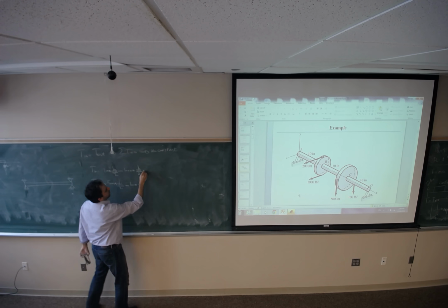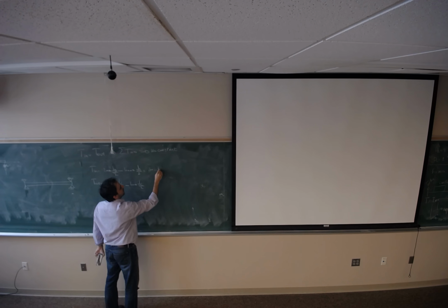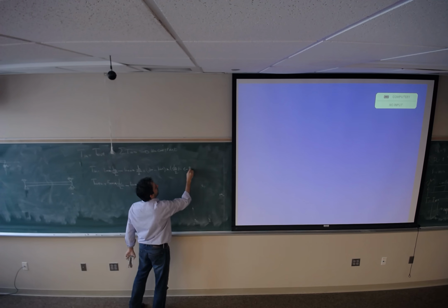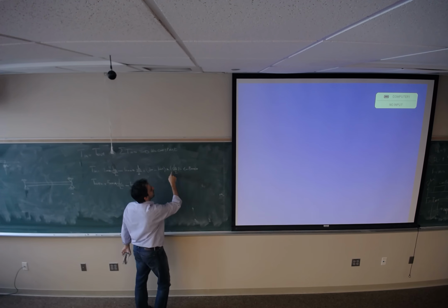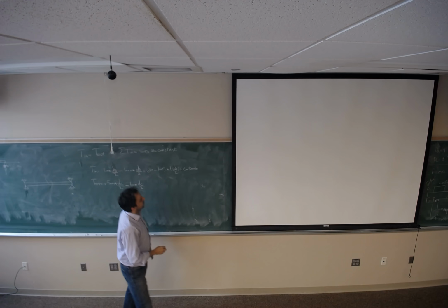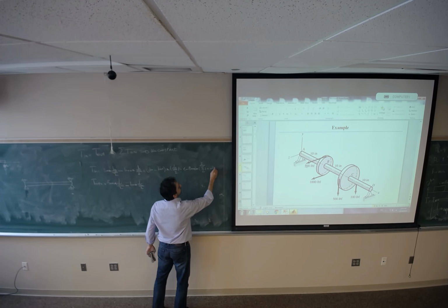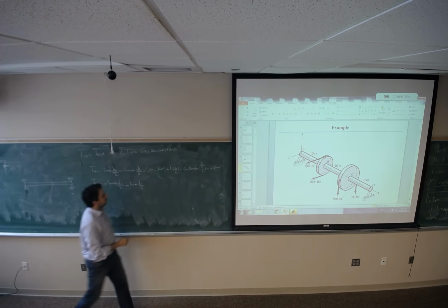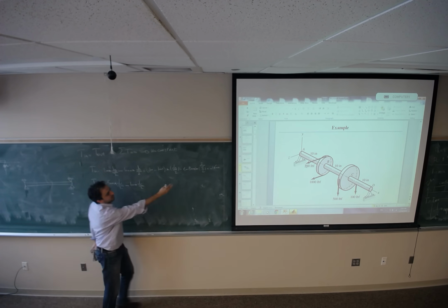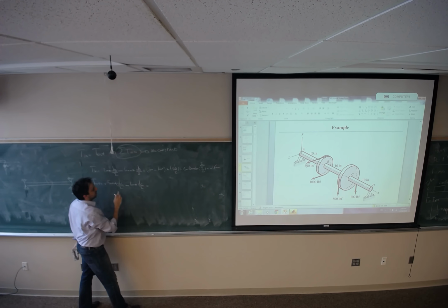So dB is 4. It's going to be 200 minus 1000 times dB divided by 2, negative 800 times the diameter of pulley B, which is 4 inch, divided by 2, giving negative 1600. We should get positive 1600 for the output, then the summation is going to be 0. If it's not, then the summation of the torque is not 0, and it's going to accelerate.